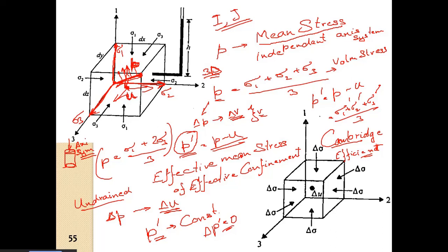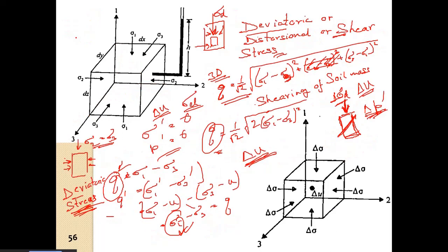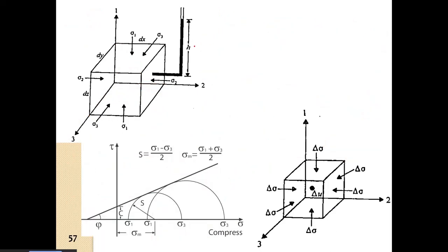Before this PQ notation was developed, we call it PQ, where P is confinement and Q is deviatoric load. Before the Cambridge notation was developed, we had another notation, we call it the MIT notation, for defining average and shear stresses.